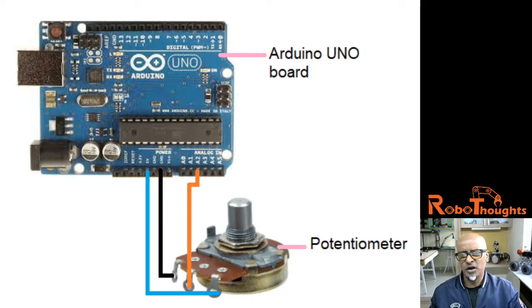So basically how does this entire operation work, guys? The middle terminal of the potentiometer is connected to the analog pin to read the analog data. It reads the information from that particular pin. And the potentiometer is basically a 3-terminal device. There are also 4 and 5 terminal ones, which at a later stage, if it is required, I'll cover in a separate lesson.